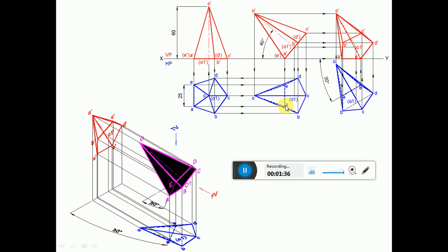Then you measure the distance from A to this point. From A you mark that point. You will get this point. Since this OC is perpendicular to AE, now we have come up to this point. From this point, by using the protractor you measure an angle of 90 degrees with respect to AE and then draw a perpendicular line to AE. Then you measure the length from this point to O.